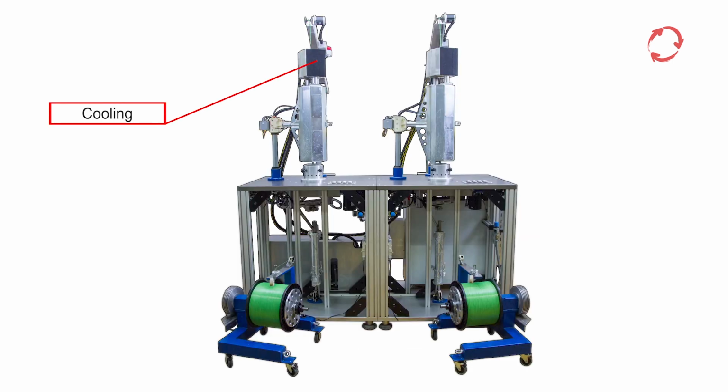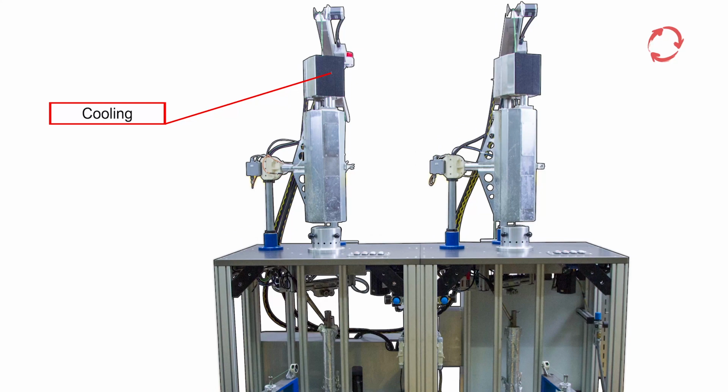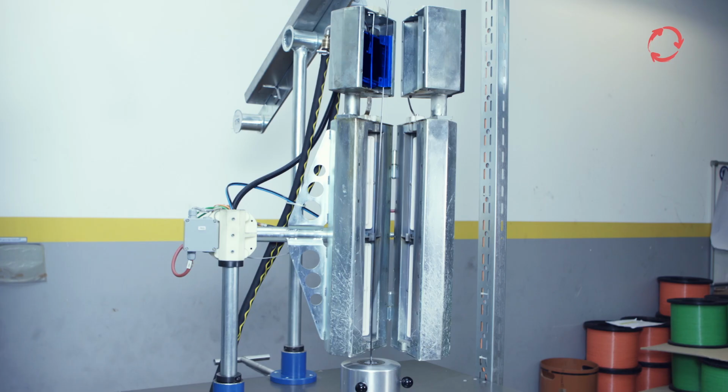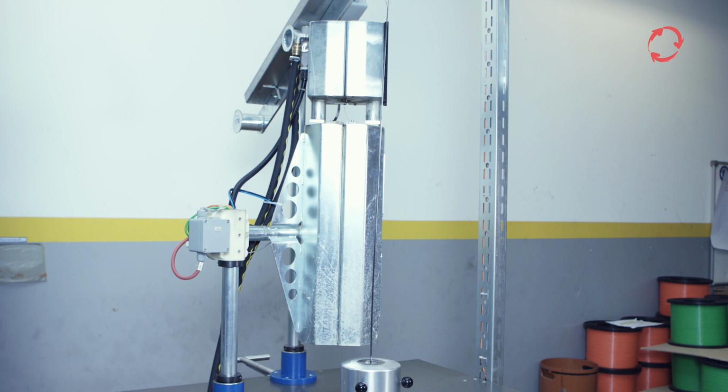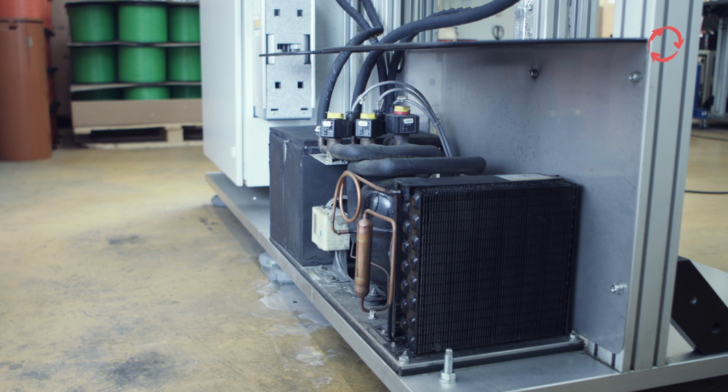The cooling unit is located above in a two-section housing, integrated into the two-part heater housing. The spirals moving up out of the heater are cooled back down in the cooling unit in order to compress them, and to allow for spirals to be manufactured from thick monofilament. Cooling occurs via the cooling unit installed on the backside of the machine.